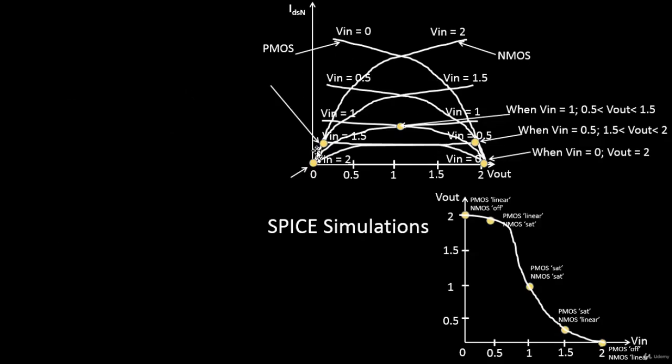So now this particular circuit has to be fed in with some waveforms to identify the output characteristics. For example, you take this PMOS transistor and this NMOS transistor, and the characteristics of them will look something like this. These curves, which I will be talking about in some time, are basically the characteristic curves of NMOS. They describe NMOS transistors. And an inverted form of these curves describes the PMOS transistor. Then you feed these two, you simulate this transistor using spice, and you get a waveform something like this. And this particular waveform will actually decide the delay of this particular cell.